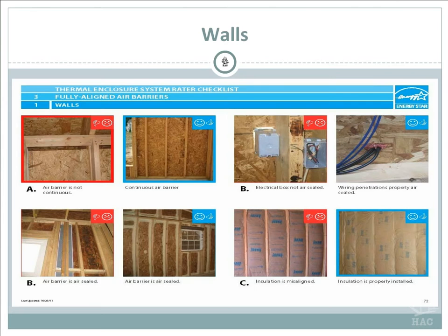Back in the good old days when I had a crew, they used to hire us just to come in and do all the air sealing and caulking. I used to tell the kids working for me, if there's a nail there that's kind of loose and you think air's coming through it, caulk it. You want to seal everything coming into that house, because what's going to pay off in the long run is your blower door testing, and we'll talk about that.